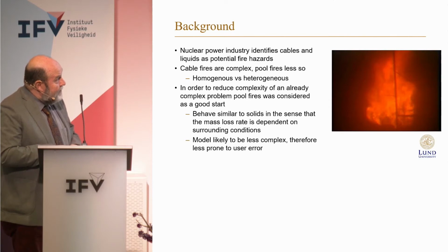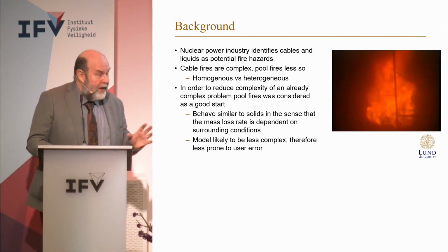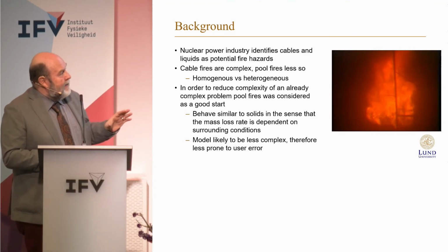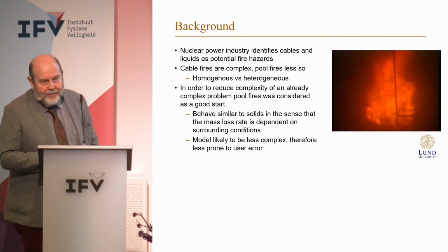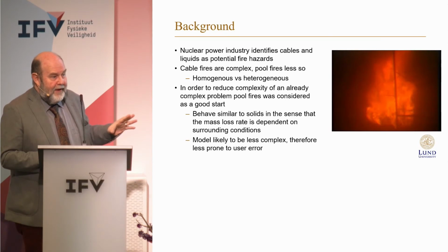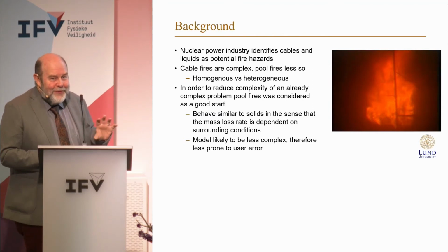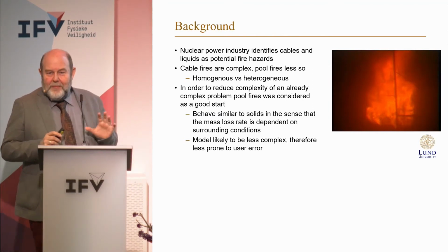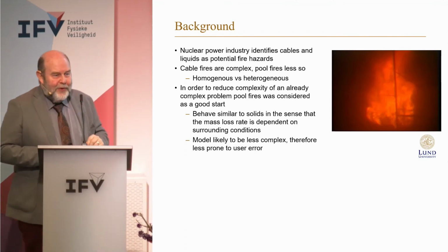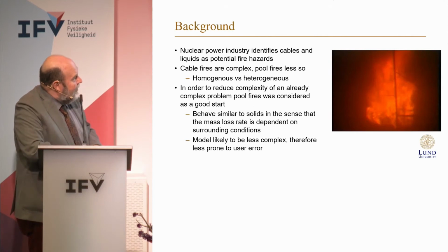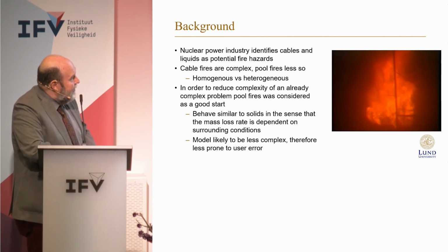And what you see in the picture here is typically a one-room, mechanically ventilated setup with a pool fire, and that's what's happening if you have, for instance, 15 times renewal: you get a quite under-ventilated fire. In certain cases we also had, which we could model but could not see because the video was just one black thing, so-called ghost flames, where you had a flame here, a flame here and there. So not so funny, interesting but not funny fires.